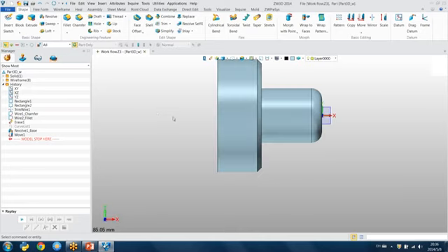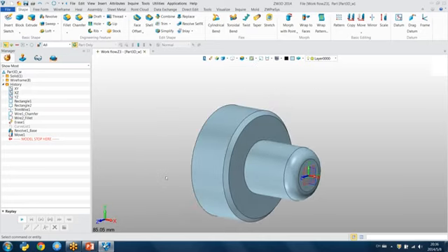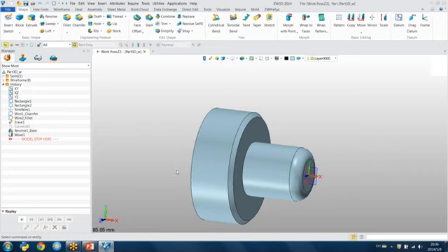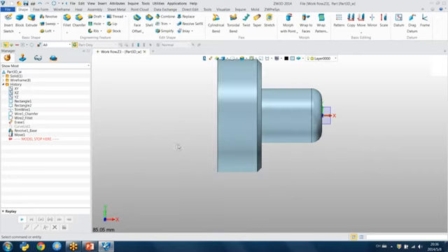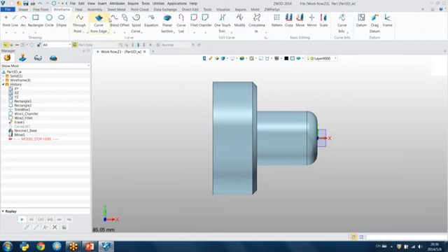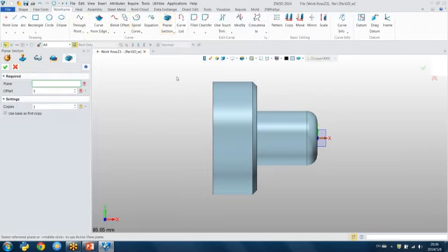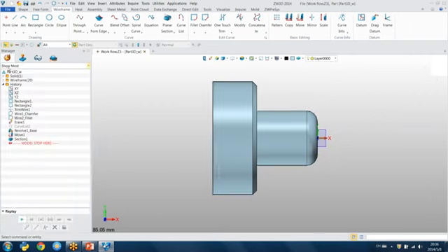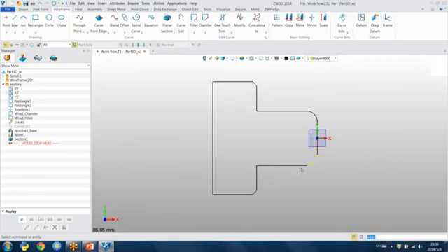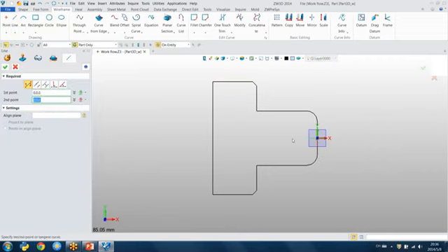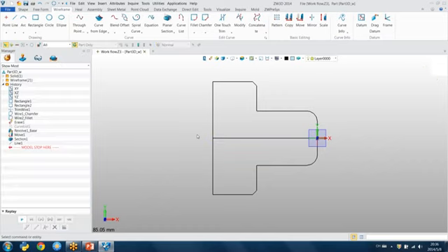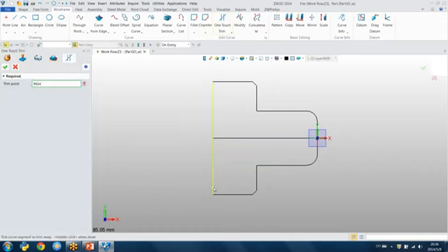You can find this is a part, a very simple part. The workflow in ZW3D is that you need to use the wireframe plane section. Choose the XY plane and the offset choose 0 and press OK. I blank the part. You can find this is the section profile. So I need to join another line and chain.